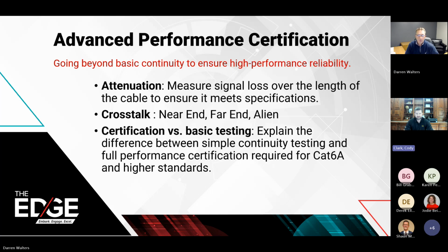So like Darren said, that previous testing identifies a lot of common problems during installation. And as a technician out in the field, we used to always carry 4 pair testers, which perform those tests that Darren just went over. And it's a good first check to identify common problems. Now, what it doesn't do is tell you, is your data going to be transferred properly with minimal packet loss and issues? And that is why we have certification devices.